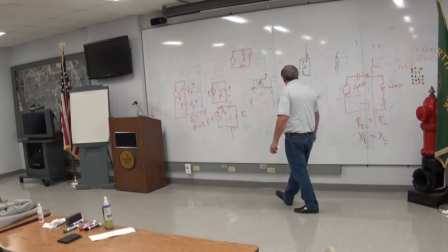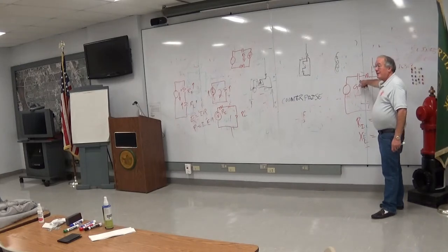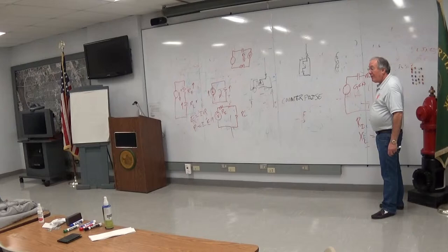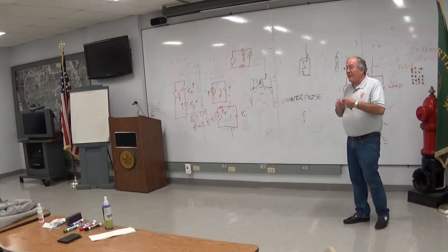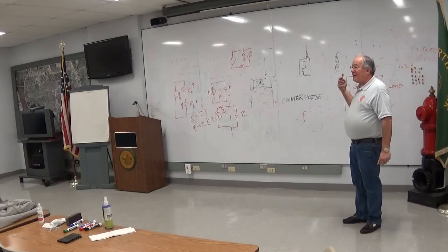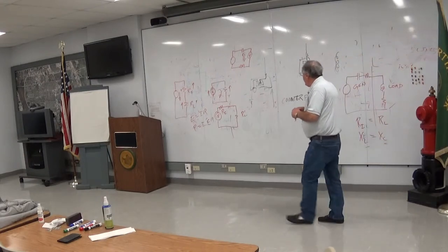You want your transmitter's reactance canceled out by your antenna's reactance, or more appropriately, your antenna's reactance is going to be determined first, and you want to do something on the transmitter side to adjust for it. If your antenna is too short, it's going to look like a capacitor.